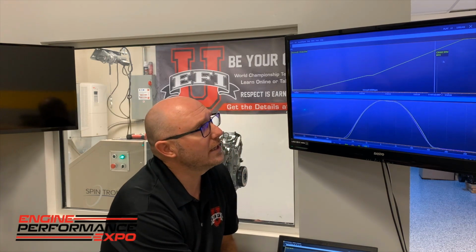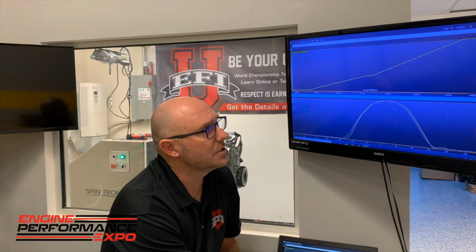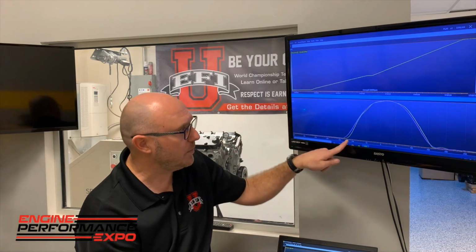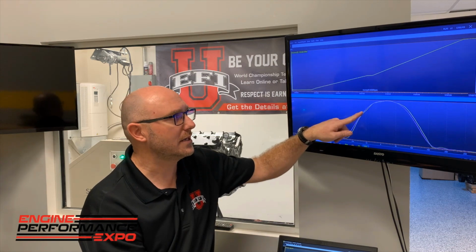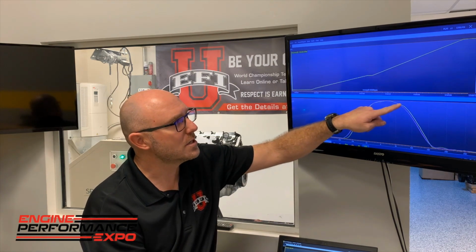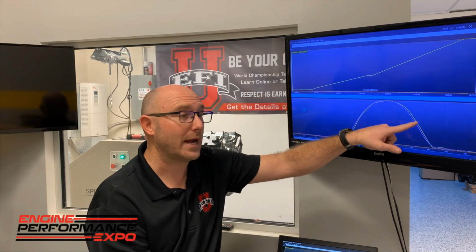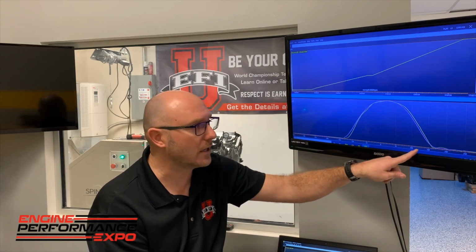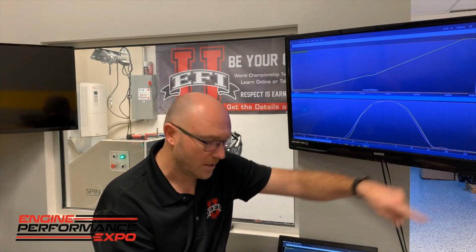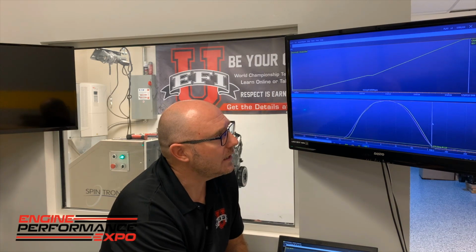So if I scroll over here, we can see when we go up here to the limit speed of this particular combination, I see quite a bit of bending and deflection on the opening side. Things kind of normalize and it catches back up as we go over the nose. And then it sort of tosses off a little bit or floats down the back side of that ramp. And it comes down, it crashes, and then you see this yellow line, it goes boop, comes back up again.